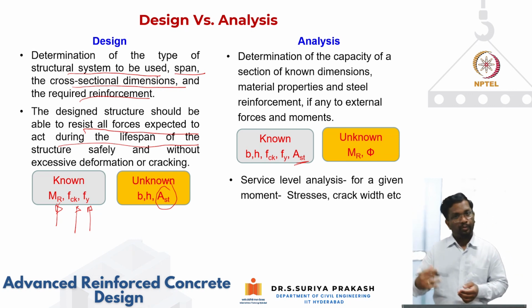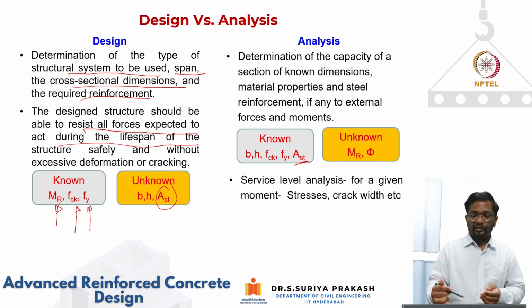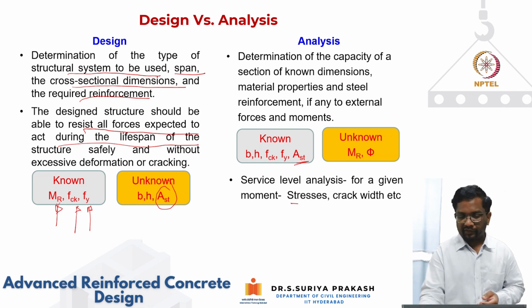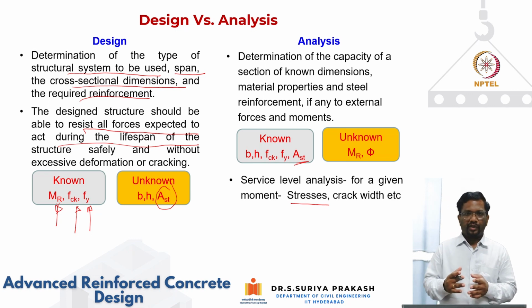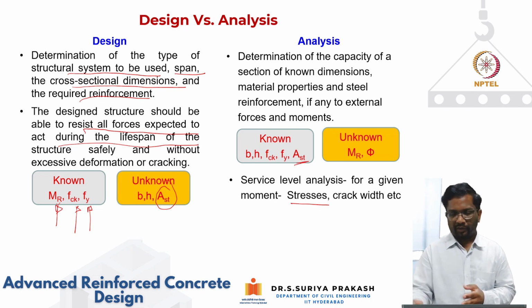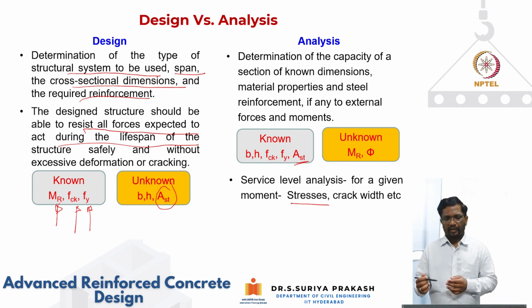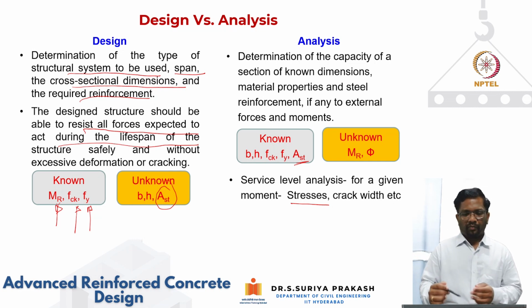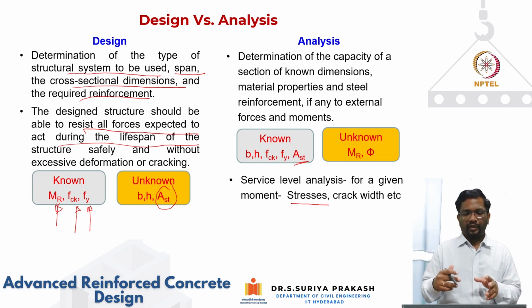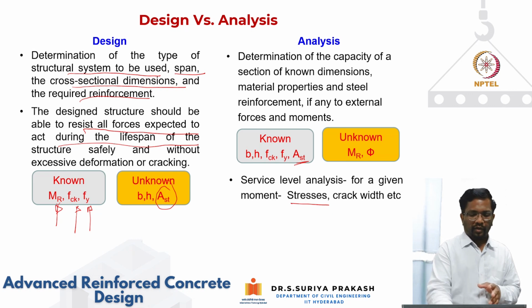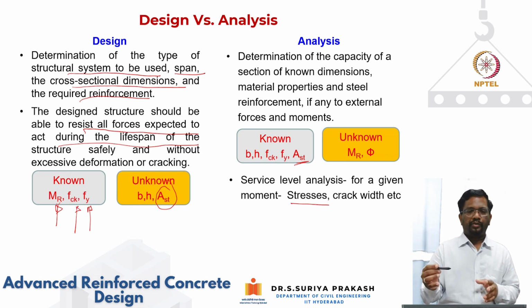Sometimes for service moment, we do analysis to see what level of stresses are acting on the steel and what crack width is going to be there under the service moment, and so on. So these are service level analyses. As I said, in design we also do analysis, but design is an iterative process. Usually your ultimate moment requirement will be given to you in design.